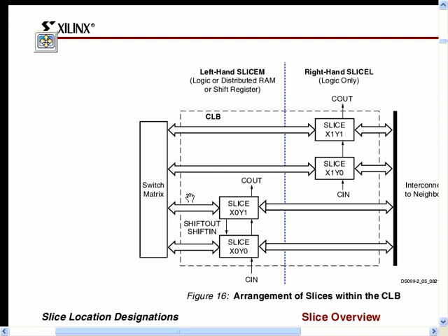Every FPGA has its own architecture, its own connection mechanism. But once it is in the same family, Spartan 3 FPGA, whether it is a different version, they have a similar architecture. In the Spartan 2 family, each CLB will have 2 slices. So a different architecture. Altera follows a completely different nomenclature and different architecture and everything. We shall see some examples.